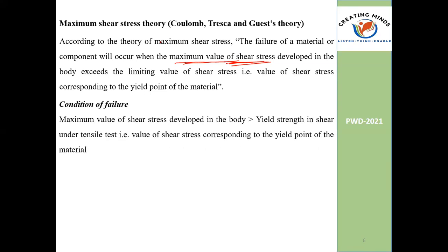What is the condition? This is the thing you have to remember. Here, with the major principal stress and minor principal stress, whatever value you get should be less than the value of sigma y. So sigma 1 minus sigma 2 less than or equal to sigma y. Clear?